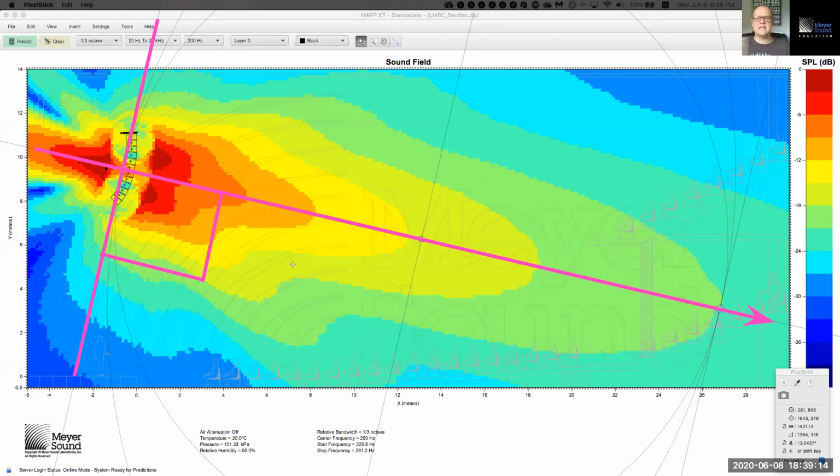And that's always the case for that concentrated beam of energy. At these low frequencies, where the loudspeakers barely stop being omnidirectional, the orientation of that beam is always perpendicular at a 90-degree angle to the array as a whole. And that is something that you will always see time and again once you start to look for this behavior.